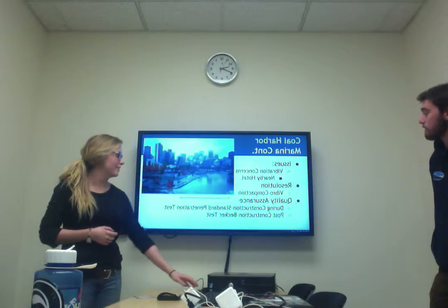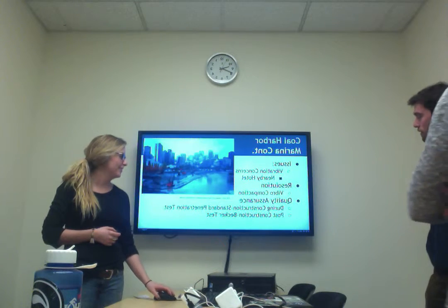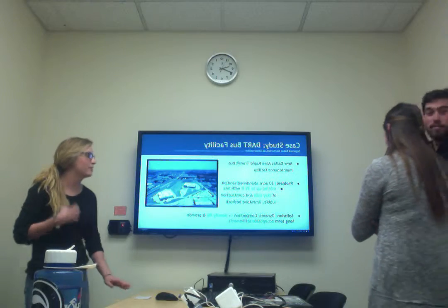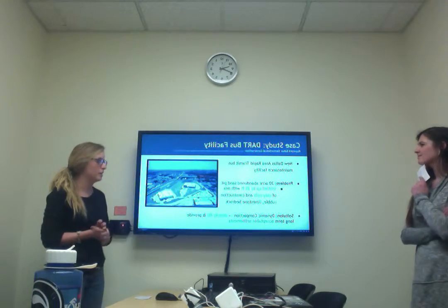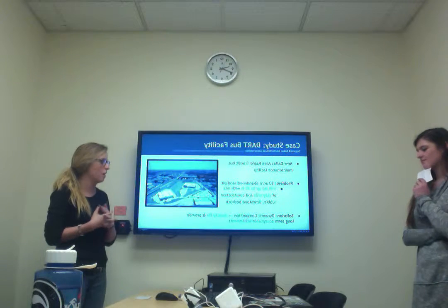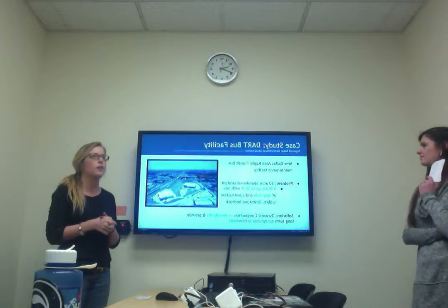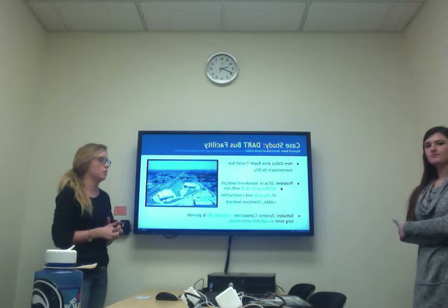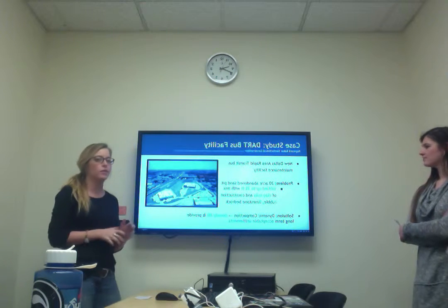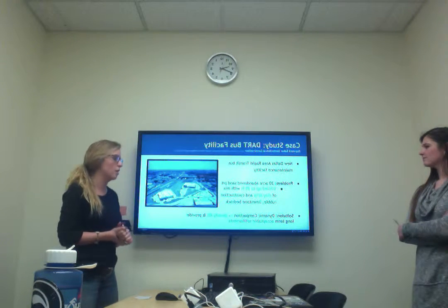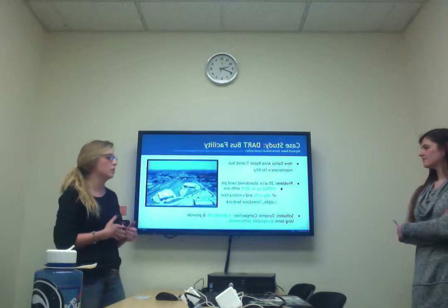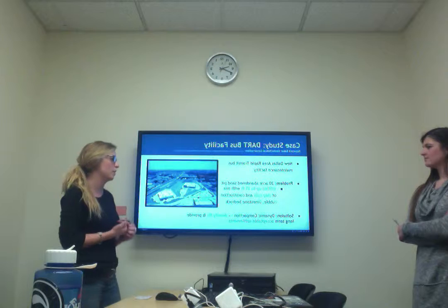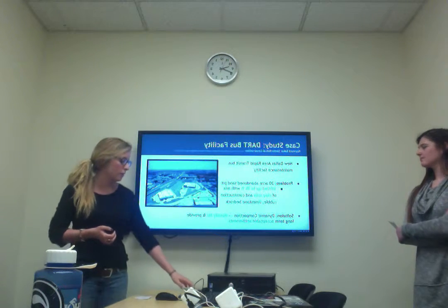Okay, so the next case study is the DART bus facility in Dallas, Texas. They were trying to build a new maintenance facility, but the problem was that it was on a 20-acre abandoned sand pit that was filled with clay soils and construction rubble, and then underlain with limestone rock. So the solution that they came up with was dynamic compaction to densify the fill and provide long-term acceptable sediments for the foundation.